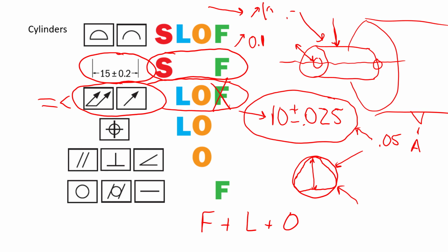The caveat to that was what I mentioned earlier, which is that the dial indicator will still pick up this, and it may still contribute to that tolerance in your measurement. But when it comes to design control, the form can never exceed that size tolerance, and then the location and orientation could never exceed your runout tolerance.